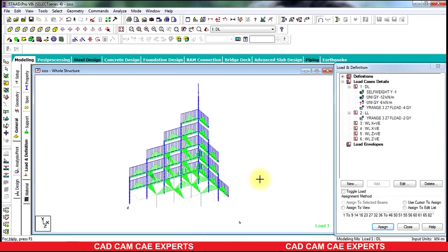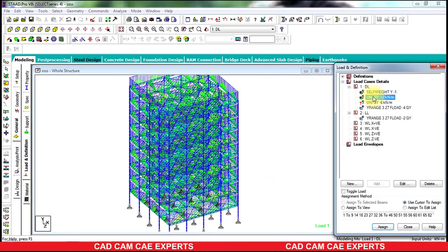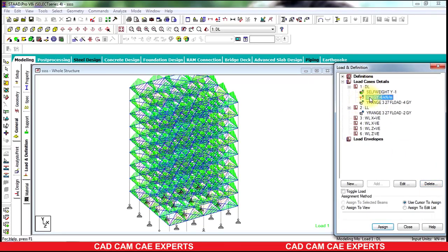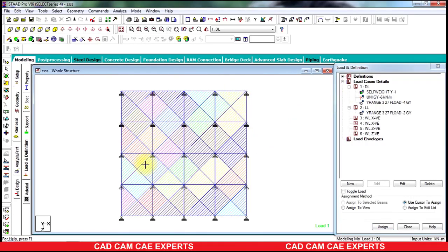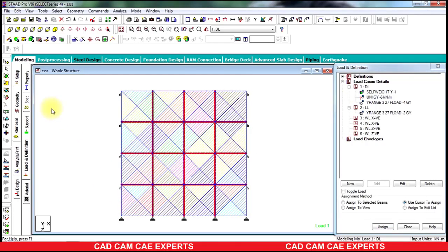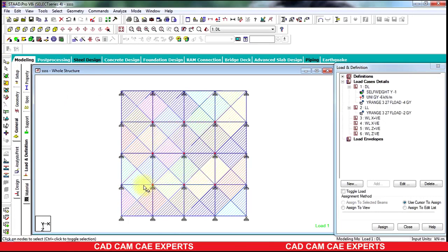Okay, you just made a little mistake. You delete this. Since you need to apply this to the interior walls, you select all the interior walls and then using node cursor you remove all the columns.